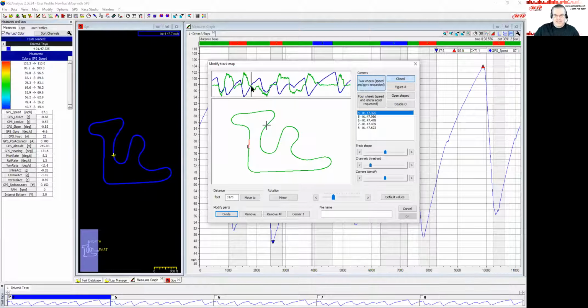So this looks like a really good spot where you've done this hard right-hand turn, you've opened your hands up, and you're starting to move the car over a little bit before you actually do this harder left-hander right ahead of us. Maybe back in here where you're right when you've opened your hands up, plus a little bit more to stay away from transitions again of all types. That might be a great spot. Then we can report in our split reports exactly how much time we spend in this whole section here. So let's divide it there.